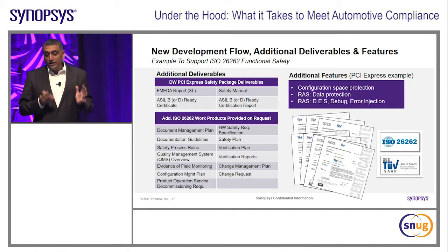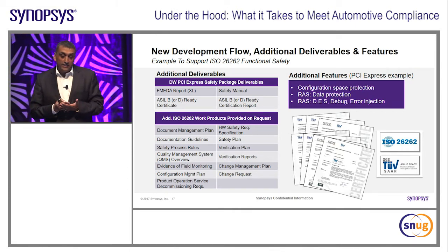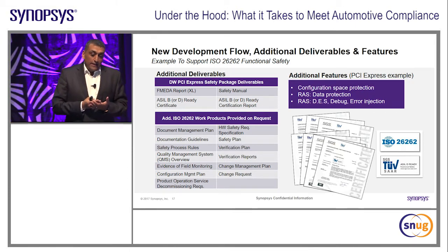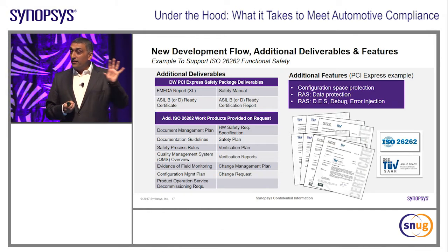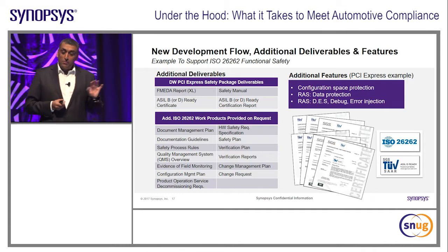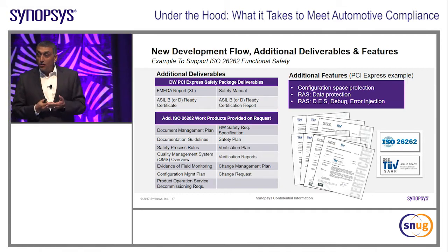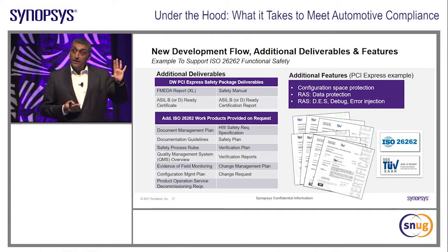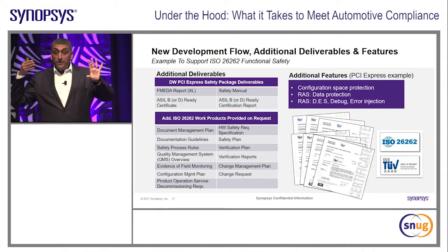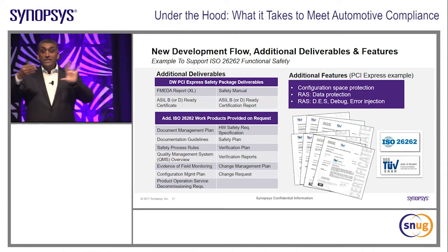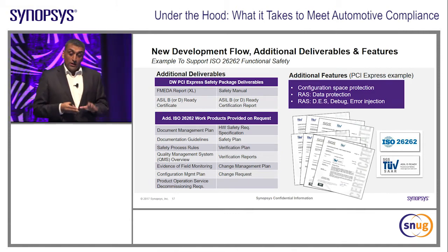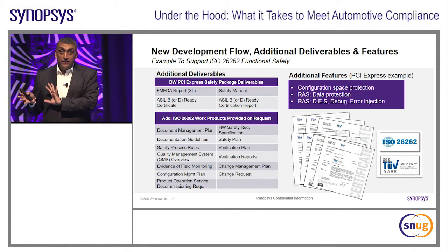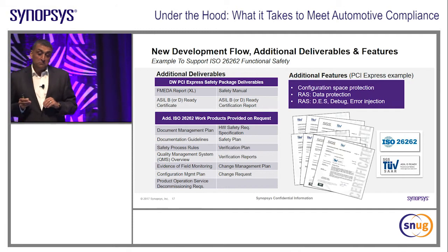So there are trade-offs. And one of the interesting things is that we talk about safe IP in terms of it's met the functional requirements, and we talk about IP that's not safe. In some examples, you can combine safe IP in a protocol with IP that's not safe and make it safe. So the example here is like PCI Express, where you have a high-speed SerDes for the electrical interface.